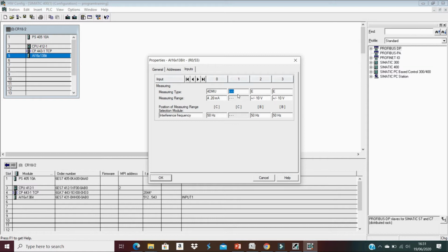Normally, why do we deactivate? Because no one should give connections here. It will not cause any malfunctions. If it is not required, we can put deactivate. But every time, whatever the channel here, we can put the same thing here, because if any problem happens during the running time, we cannot download the hardware configuration directly, because it will go to the swap mode.